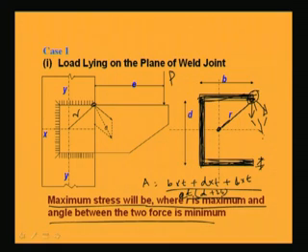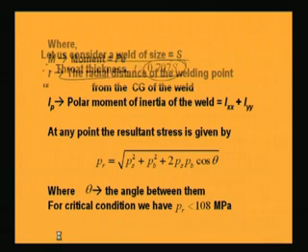Here also notice that E is not exactly this one. For calculation, E will be the distance from the CG to the load. So the eccentricity from the column face plus the CG distance will be E, and while calculating, E has to be calculated accordingly.